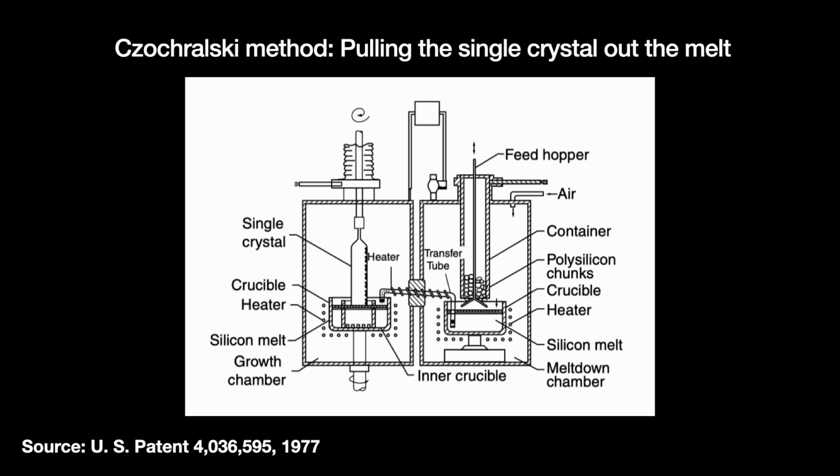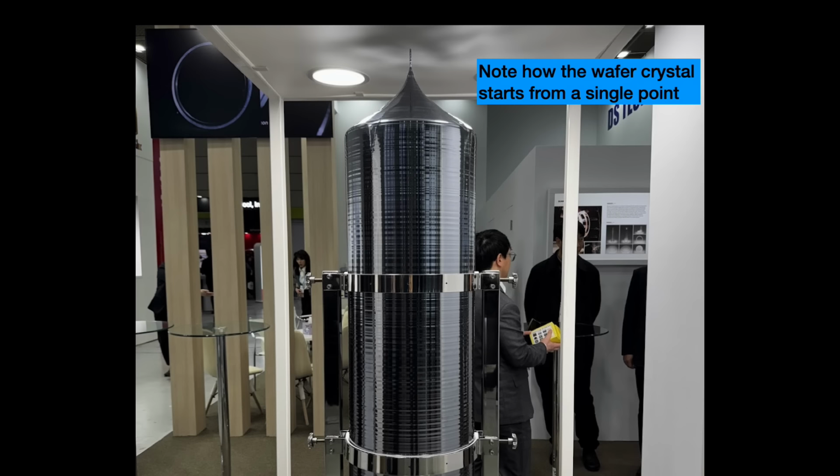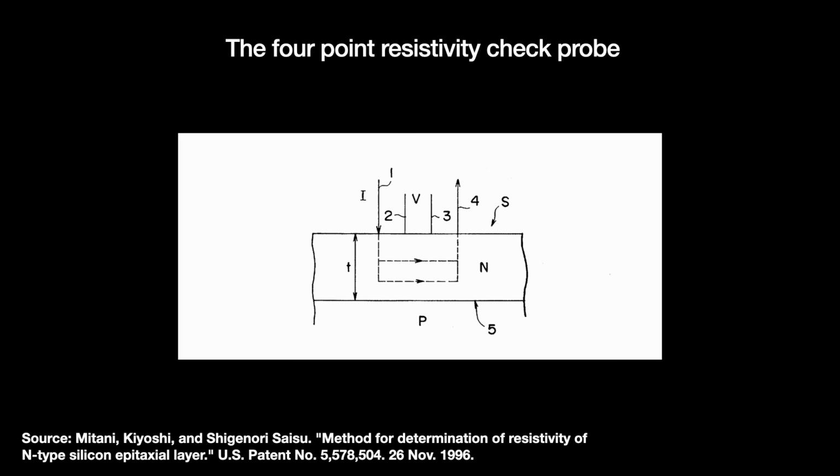If these impurities get incorporated into the transistor, especially metal impurities, then it will cause the transistor's threshold voltage to fluctuate, and then the transistor might not switch when it is supposed to. So we check for impurities by measuring the silicon wafer surface's electrical resistance against the specs. A 4-point probe is lowered onto the wafer surface and runs a current from one point to another.